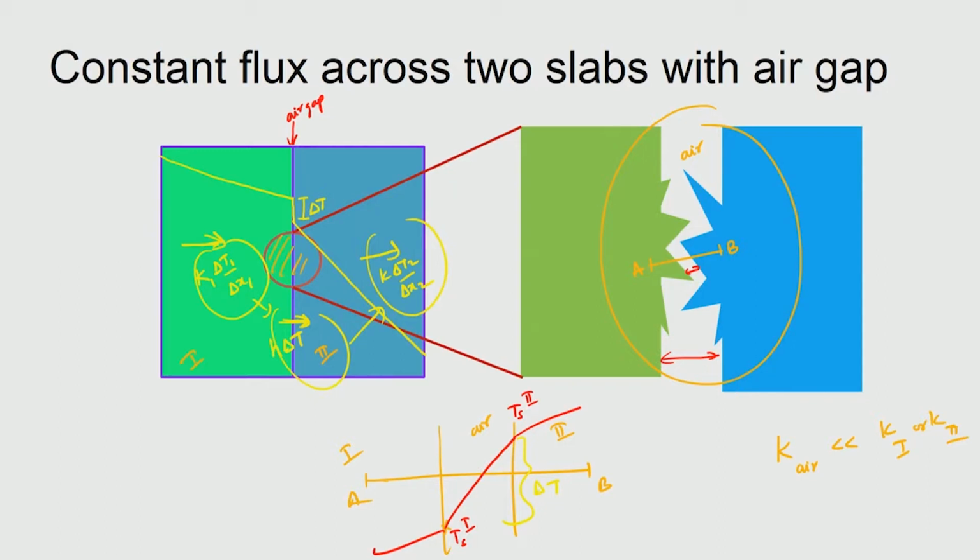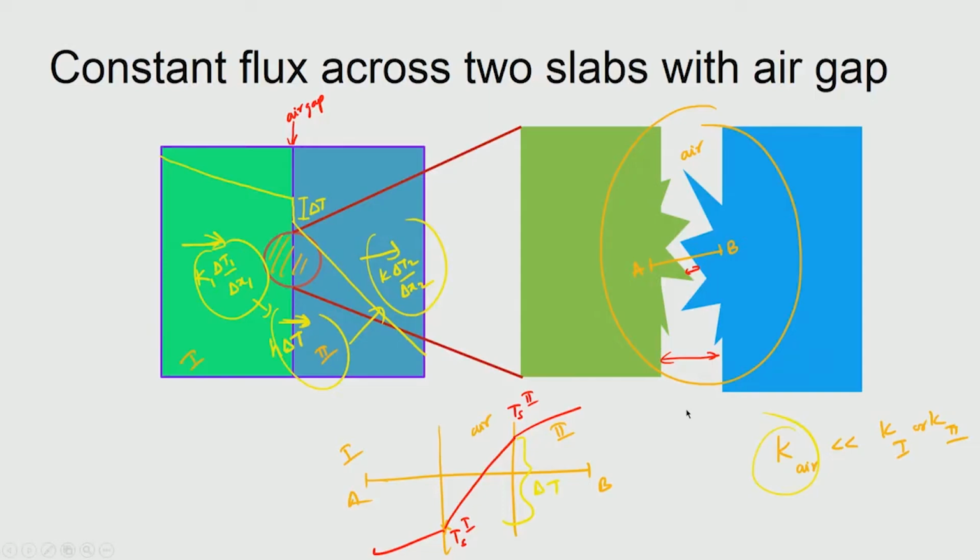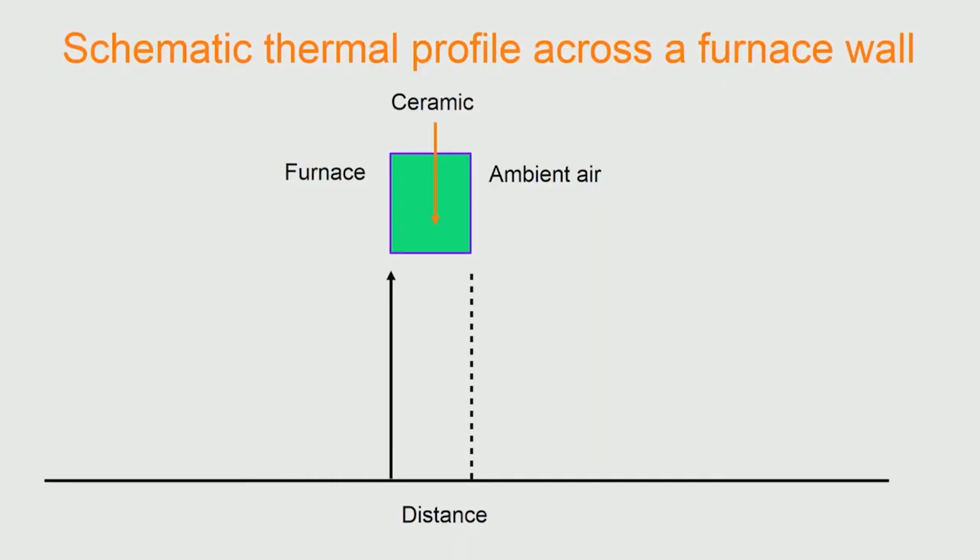In the case of situations like continuous casting, this actually plays a very big role. We do have this air gap between the caster and the metallic material that is solidifying, and inside this air gap we try to introduce ceramic materials to control the thermal conductivity and thereby achieve different cooling rates to avoid cracking, etc. So, we must pay attention, and in model problems we may ignore it, but we must know that we are making a very conscious decision that there is no air gap, which is not reality in most situations. So, let us for a moment ignore this particular aspect.